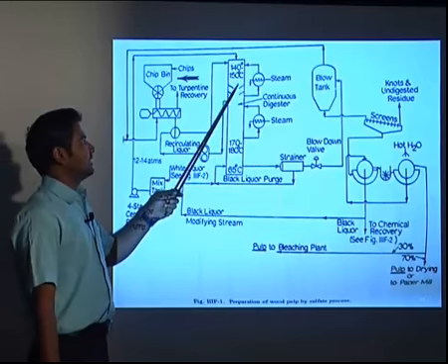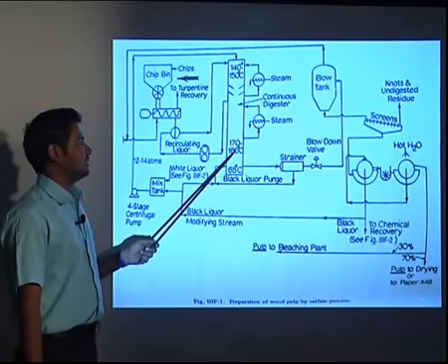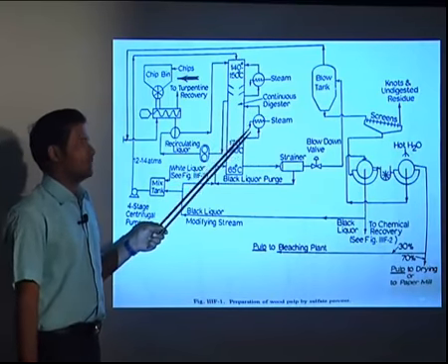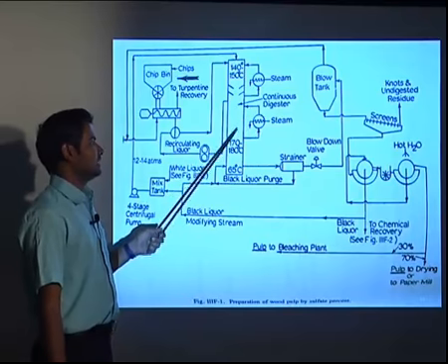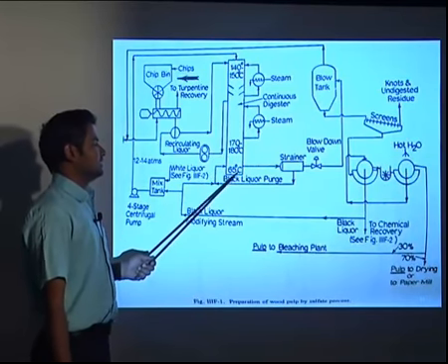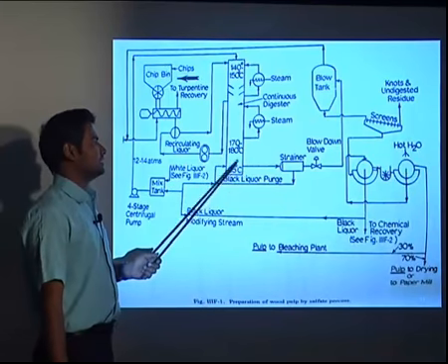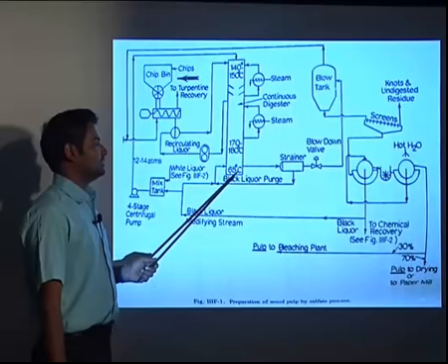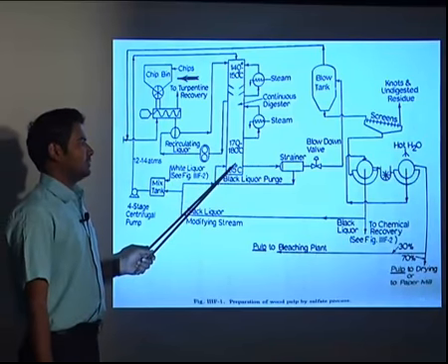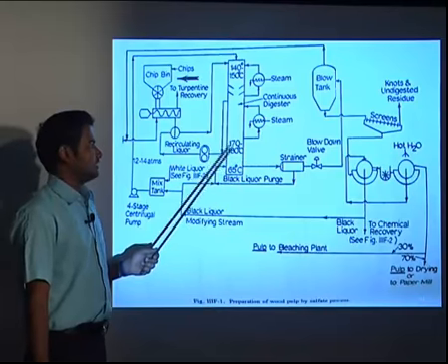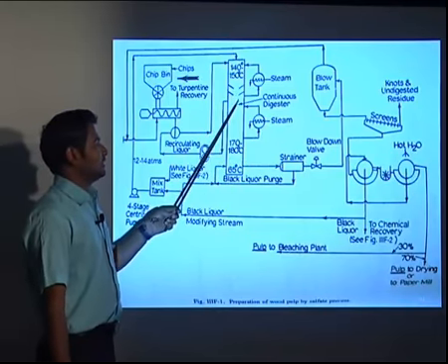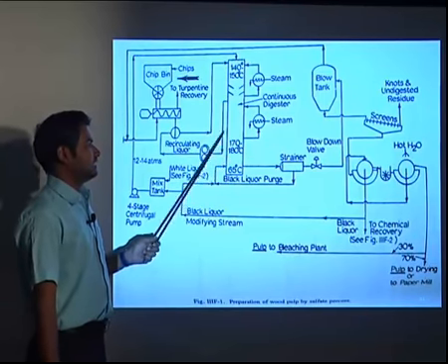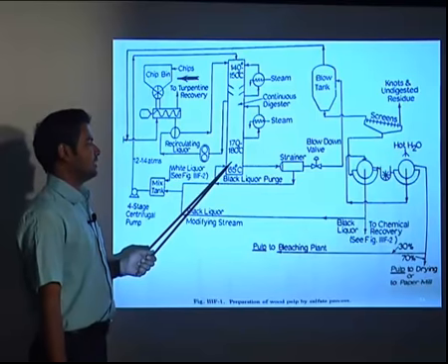The temperature is maintained around 140 to 150 at the top, and at the bottom it will be around 170 to 180 degrees centigrade. Here we have to maintain the heat so that the fibrous material will not deteriorate. And also at the bottom, the temperature is lowered by the black liquor purge. This will help the cellulose content not to get deteriorated. So the black liquor will play an important role, and it will maintain the quality of the fibers which you are getting. Then we will get the black liquor which is high in lignin content, and we will get the high quality cellulosic solution.